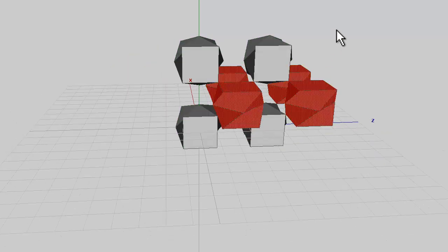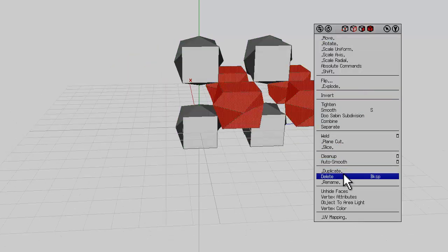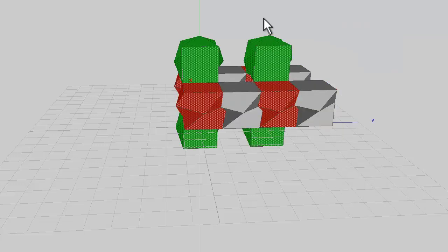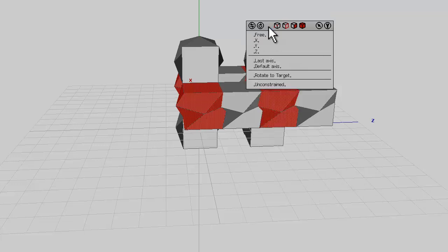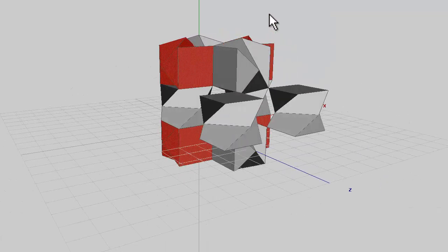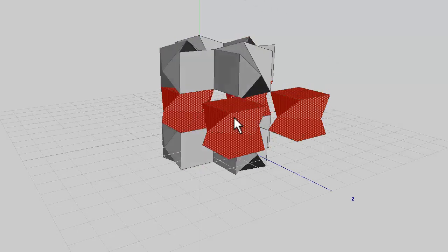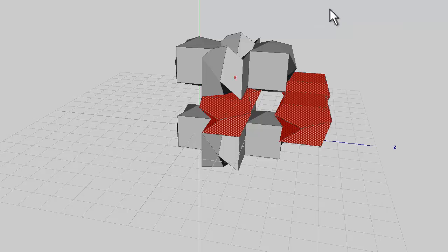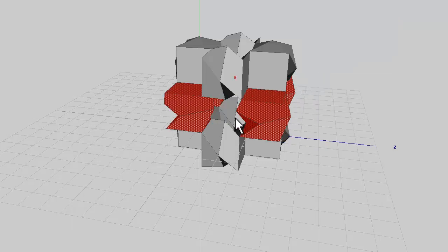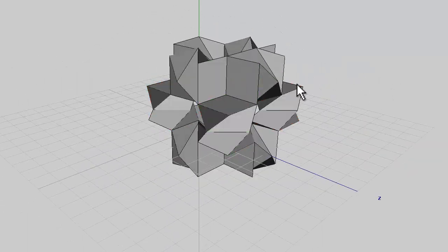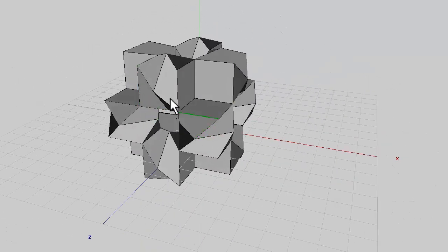and then I'm going to duplicate another set because I need another set yet, and I'll move them back to the starting position there, and then rotate them along the other axis, which is the x-axis, so they fit up like that, just holding the shift key down so I get definite steps. Then select this one and slide it into place, so that's move, not rotate, move along the z-axis there. So that's the shape you're aiming to get with each of these twisted ones, twisted like cubes in the middle of each of the face.